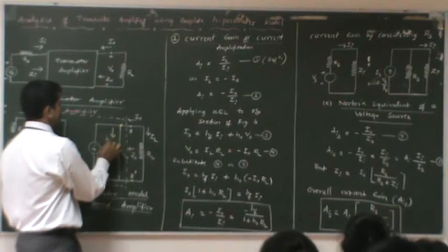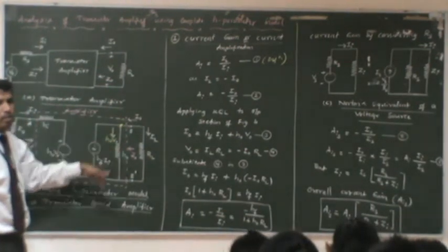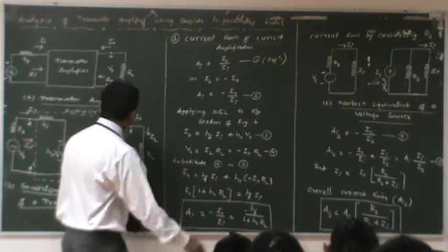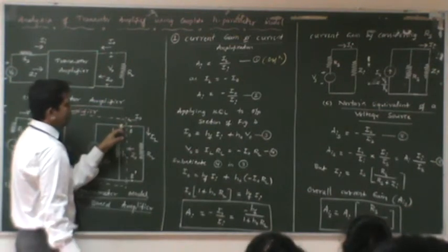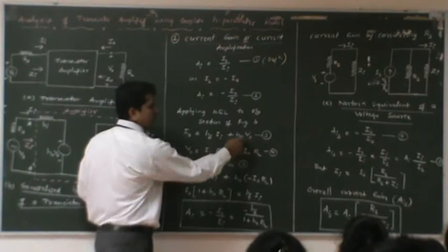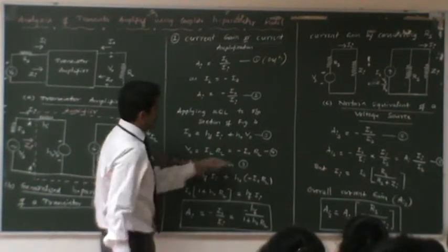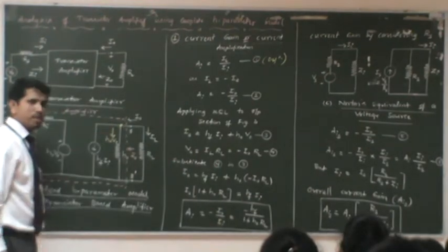This current is nothing but H0 times the V0. This is the current flowing in this admittance. It is H0 times the V0. So obviously these 2 currents are leaving and this current is entering. So as per the KCL, the entering current, which is I0, is equal to the sum of the leaving currents. So this we have labeled as equation number 3. Any questions about that?